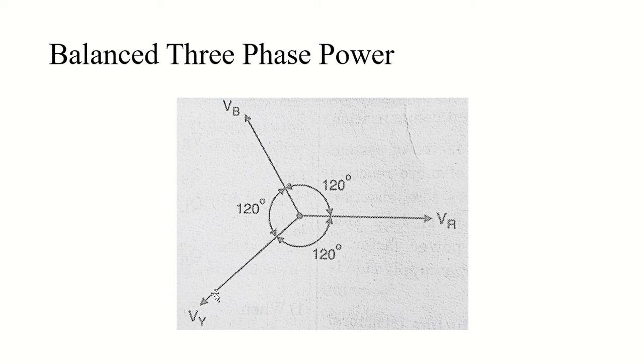It means the active and reactive power for all these phases should be similar or equal. Although we all know that that condition is almost impossible to achieve, it is very difficult to achieve that goal, and that is why we are having these compensation devices, right? Because load will never be similar on all three phases. Load will always be diverse in nature.